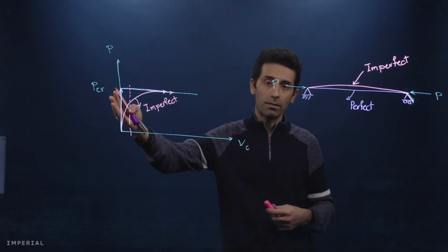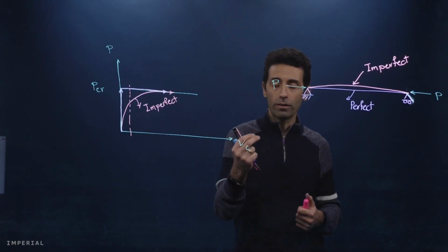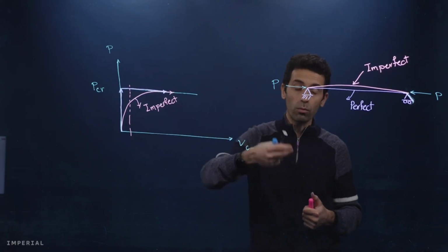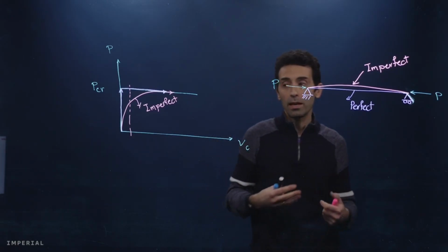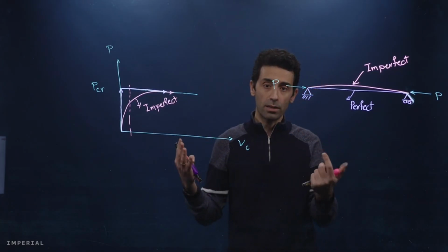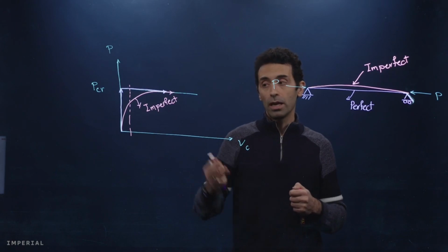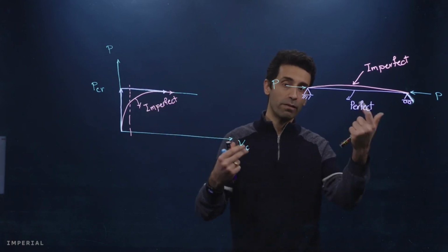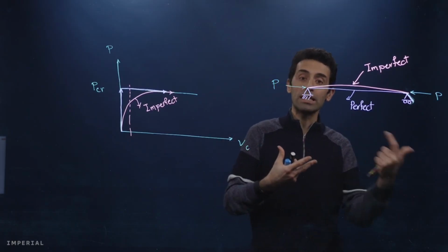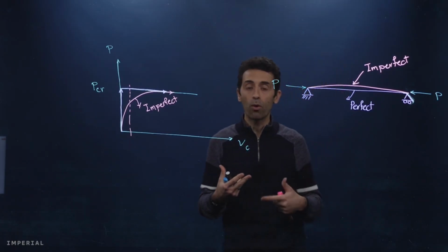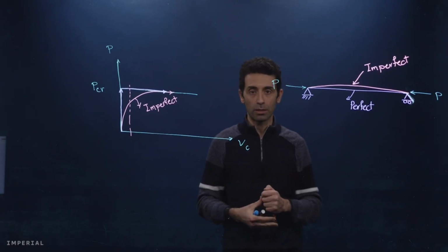Well, you shouldn't be disappointed, because the linear buckling theory is still extremely useful. It's being used to have a very good estimation of what loads should be avoided or what loads can be utilized in the design process. But you can also try to make your predictions more precise after you have had this first pass on your model. You can incorporate the imperfection in the geometry and material in your model, and then you can run nonlinear simulations that would give you a more accurate estimation of the response of your structure to the membrane loading.